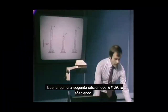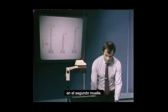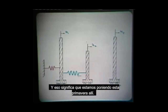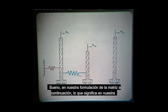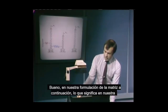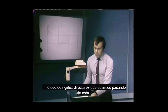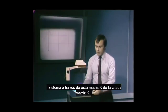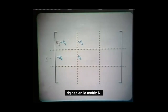With the second addition, we're adding in the second spring, K2, putting this spring there. In our matrix formulation, that means in the direct stiffness method we are going from this K matrix to that K matrix, adding the second spring stiffness into it.